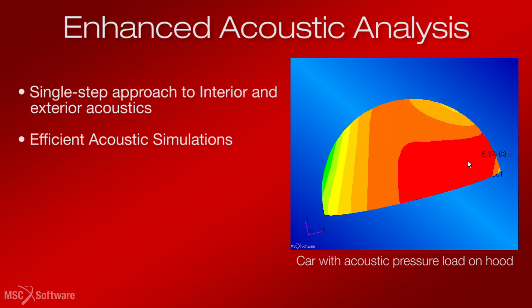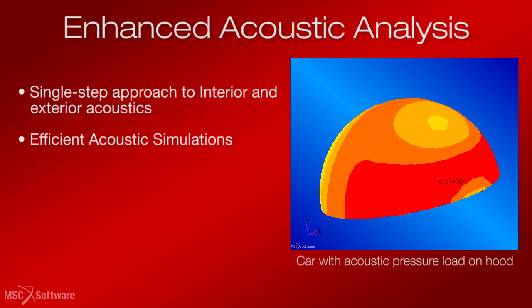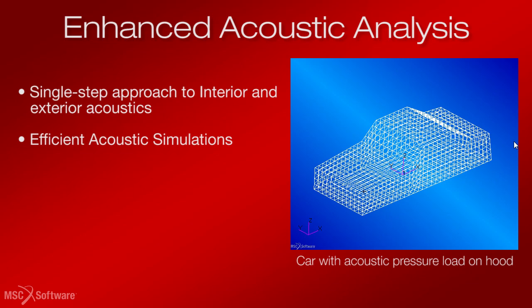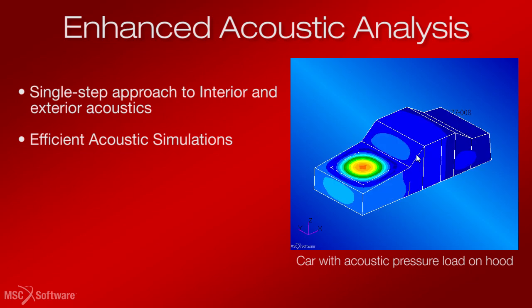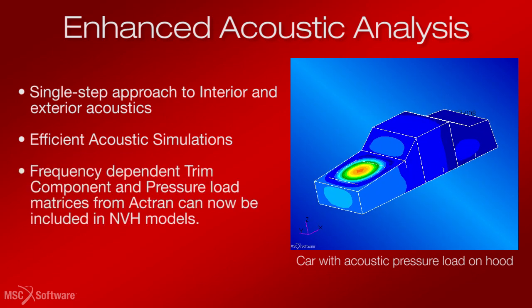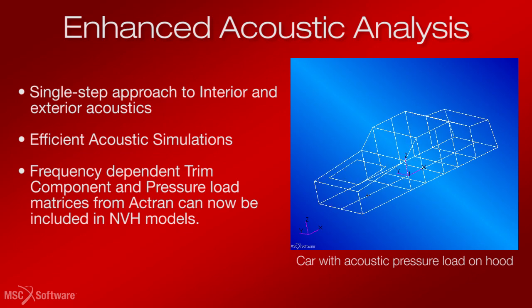Panel participation factor analysis is extended to structural domain responses, and a new function to compute and output element sensitivity for acoustic responses, along with a new function to compute the particle acceleration on wetted surface were added. Frequency-dependent trim component and pressure load matrices from Actran can now be included in NVH models.